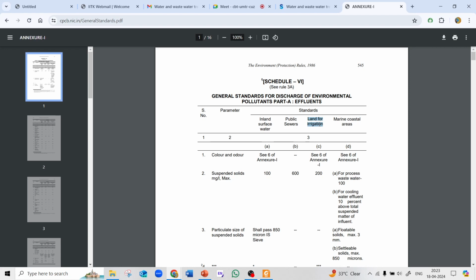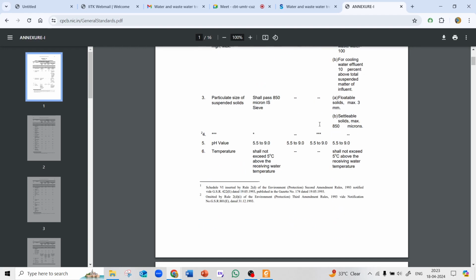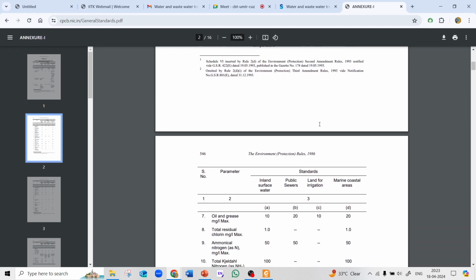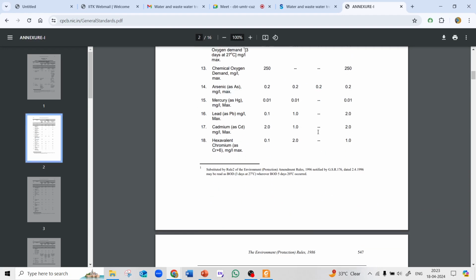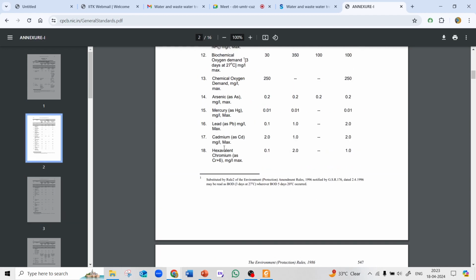How have we concluded that the water is not suitable for irrigation? We collected water from that canal and tested it in our lab, or people working in that field have tested it, and they have seen that the limits being given here are not being followed. They are discharging their water in a very unsystematic way, so that water is not suitable for irrigation. The main problem has been seen with chromium. See here, hexavalent chromium is toxic.